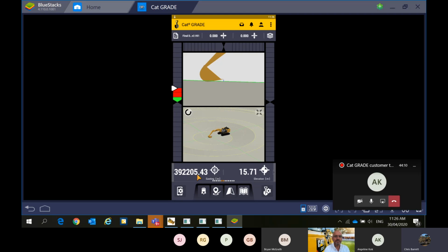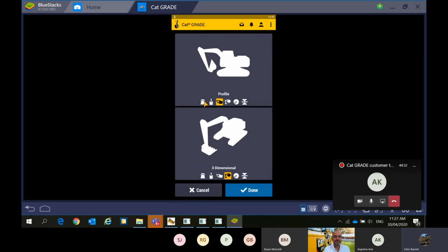By putting that machine on that known survey point, it determines whether you've got an accurate machine, a good bucket measure up, and the site calibration is going to be okay. So first thing you do before you go to work, if the machine's near the grade line or you've just come onto a new job, make sure you verify that machine on a known survey point. So we're checking for your accuracy is what you're saying? Correct. And there's a couple of different ways to do that.